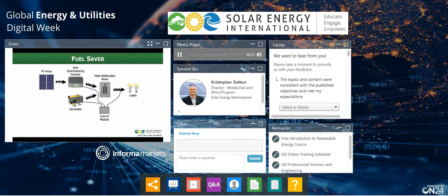So with the right control systems, we can reduce the load on the generators by paralleling solar without batteries. The generator still runs 24 hours a day, but maybe we don't need as many of them online at one time. So there has to be an analysis. It often works better in a multiple generator situation. So that's another way we can synchronize solar with a generator source to reduce fuel load in a remote area.